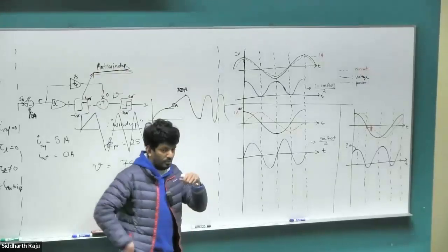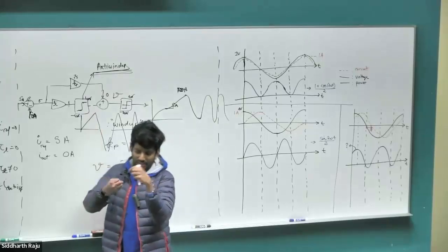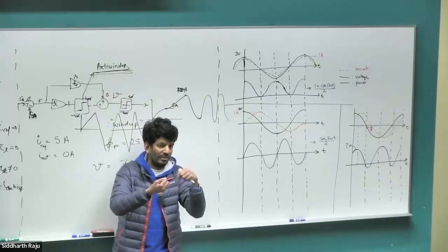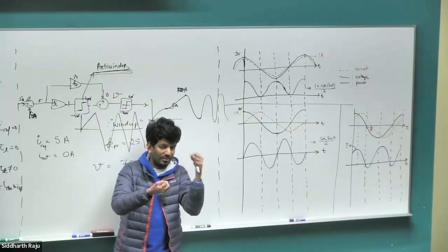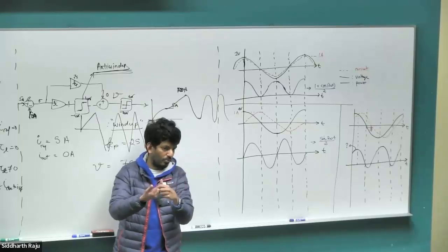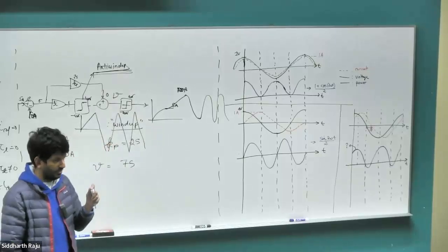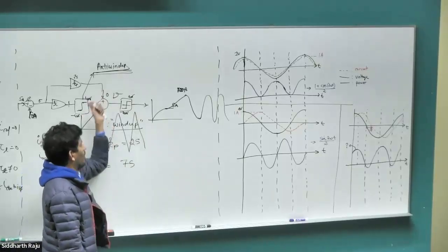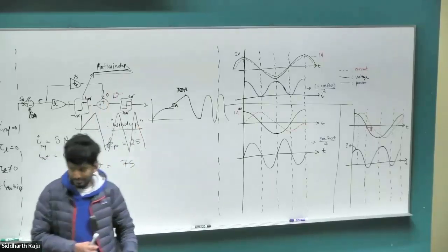So this is exactly what you have in those toys. When you twist them, they have this anti-winding mechanism where there is like a latch. So once you reach the limit, as you keep twisting it, you'll hear the gear sound grr, grr, grr. And then once it starts to hit the limit, you'll hear that click, click, click, click. There is a latch that basically disconnects the input from the output, basically preventing this wind-up from happening in your physical system. So we are doing the same thing in the mathematical world as well to avoid that wind-up from happening, right? So the name comes from basically those toys that were there back in the day.